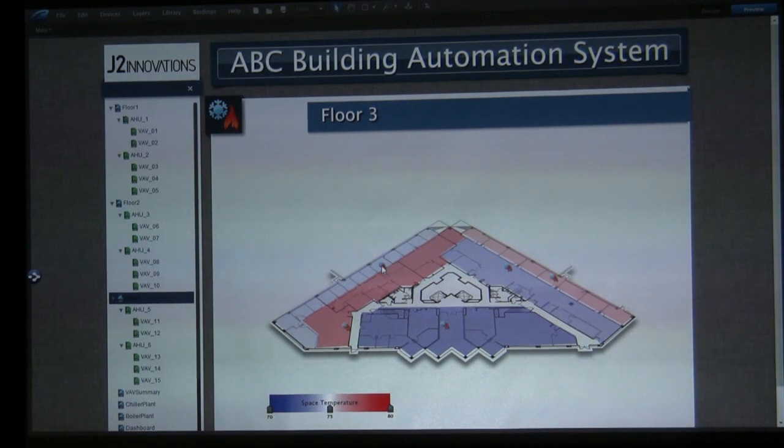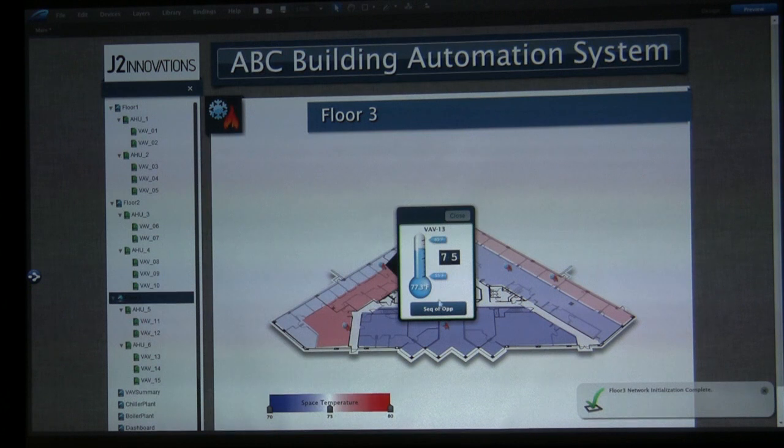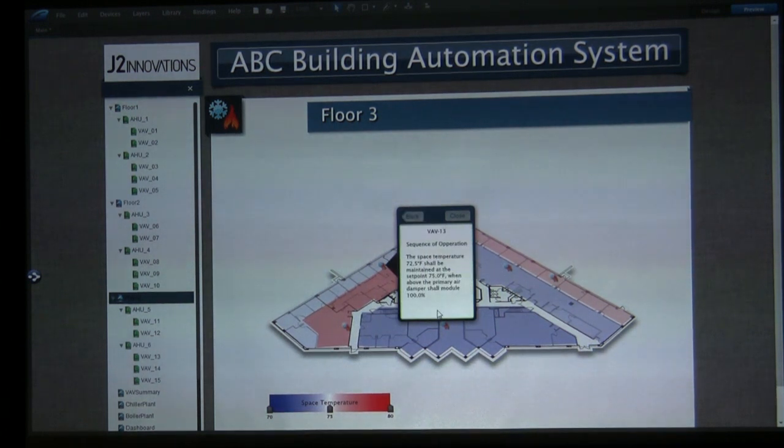Now let's take that idea one step further. I can put actions inside of my user experience that do even better things. So in this case, I'm calling out another callout. In this case, it's a sequence of operation. Now, one of the neat features is that we can do dynamic point variables right into our text box. So this text box actually is going out and taking the sequence of operation and mixing and matching fixed values with live values. So we call it dynamic sequence of operation. Another spec item that, again, your customers could differentiate using this cool feature.